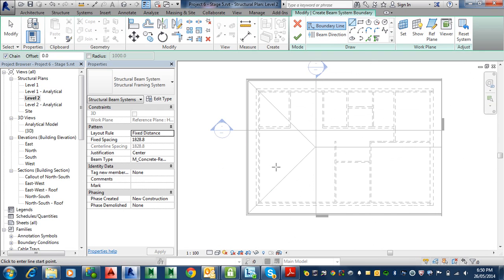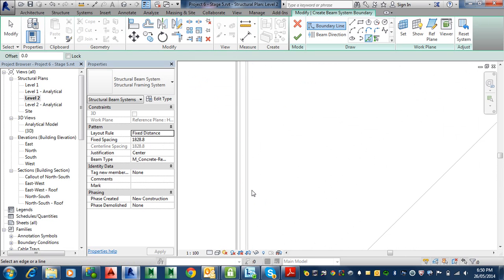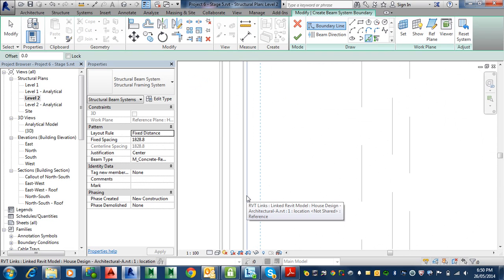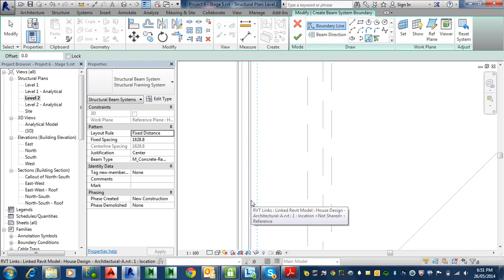Let's go with the draw panel. We're going to select the pick lines tool, and then we're going to sketch around the lines. Note the direction. All right. So basically, if I pick lines, this one here, I'm just going to go into here. This can be adjusted afterwards if need be. Now that line there is the back of my fascia, I think. It's going to draw it a bit in because that compensates for the angle we're drawing at, 22.5 degrees. Anyway, we'll put it there.